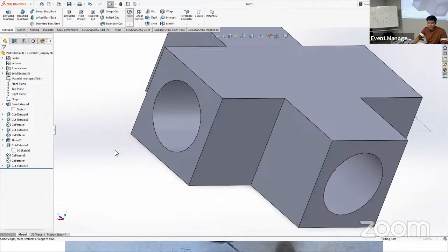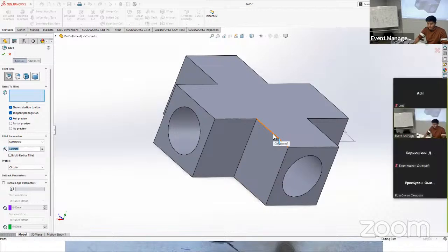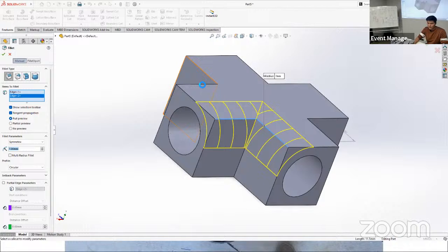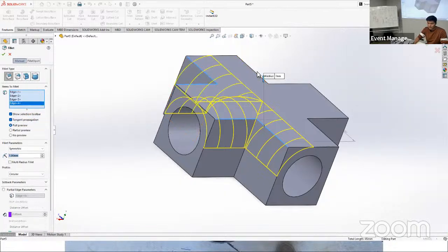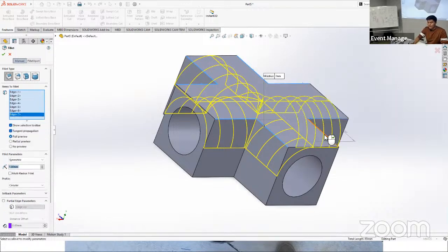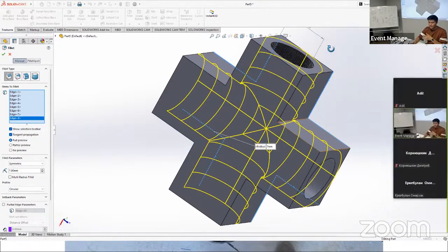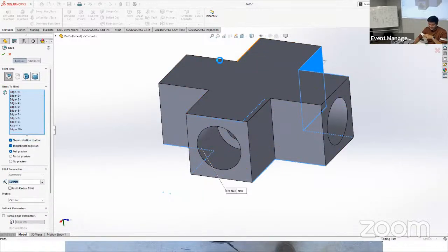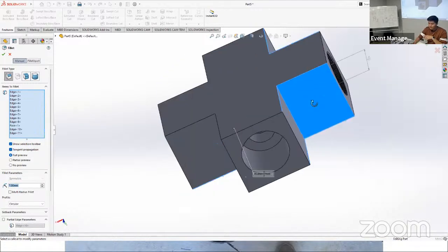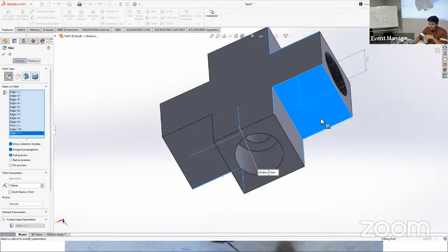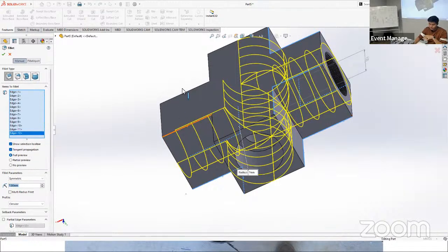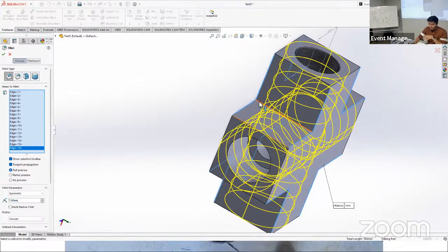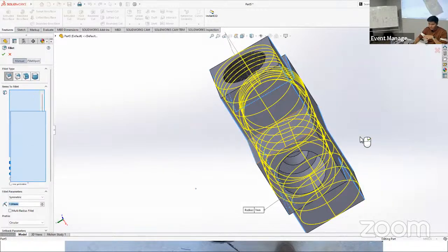And let's make the fillet again the right way. So we are choosing these corners and, okay. So it's actually very delicate work to do. When you work on more complex models, you're going to sit here and be like, oh, okay, too much labor work for my accuracy with the mouse. Okay, it shows that I accidentally selected the plane, not the edge. And actually, we can also take into account those corners for it to.